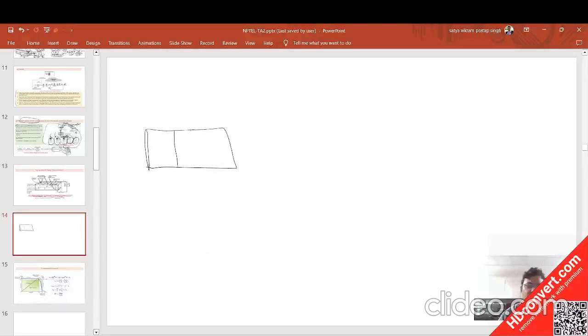Suppose there is a p-n junction, this is the p side and this is the n side, and in between you have this depletion layer with certain ions, and these are carriers, positive or negative carriers. When light is incident on this p-n junction, it is completely isolated, there is no physical contact to draw this energy out. So I am considering the first situation, the open circuited condition.